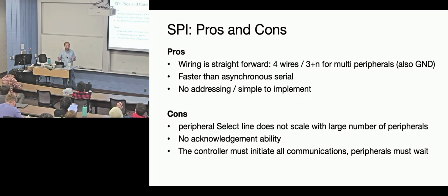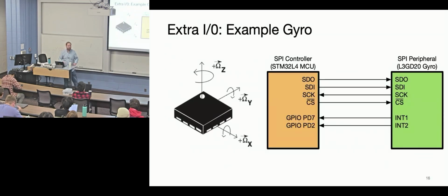You must have questions. So let's say you're trying to use SPI with a temperature sensor. Are you treating the temperature sensor as a singular register that you can read and write that just happens to get filled with the temperature, or do you use the data write line to say I want to talk to this register inside of the temp sensor? Like with the APB stuff. It depends on what the spec is for your peripheral.